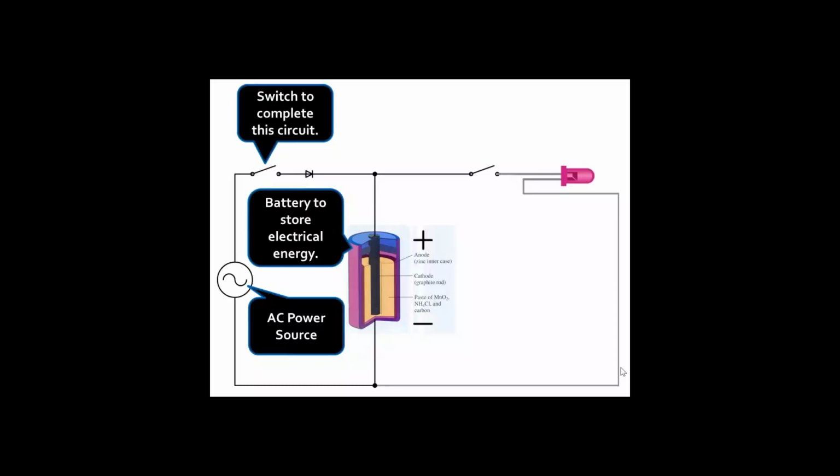That's actually a diode or a rectifier, because we have an AC source, meaning the current is going back and forth. It's switching direction 120 times a second, which gives you 60 hertz, 60 cycles. A complete cycle is current goes one way, then goes the other. That's one cycle. So you get 60 of those a second, but we only want current to flow one way through that battery, and that's to charge it. That's why we have that diode in there.